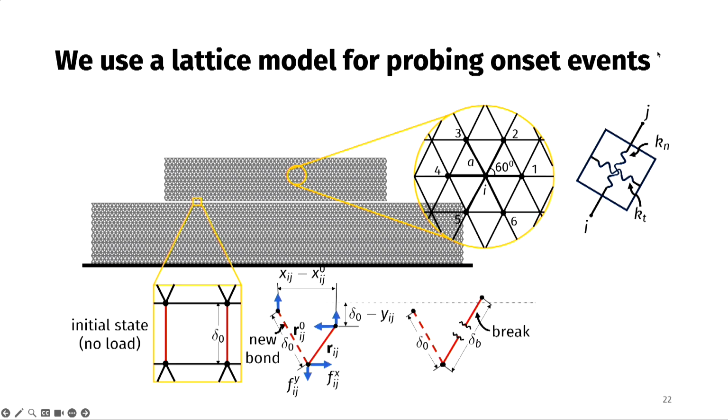Now at the interface, we put interface bonds, right? So these are all bulk bonds. At the interface, we put interface bonds. And the interface bonds are different from the bulk bonds because they're single springs and they have an initial rest length. The value of the rest length doesn't matter because it just decides how close or how far away these bodies are. And that determines the time step for the computation and so on. But it's a minor detail.